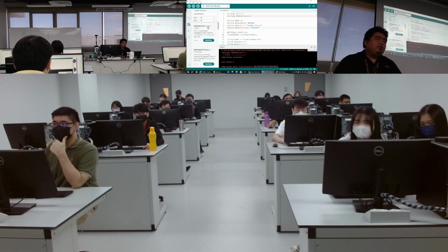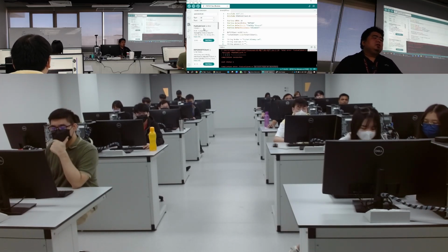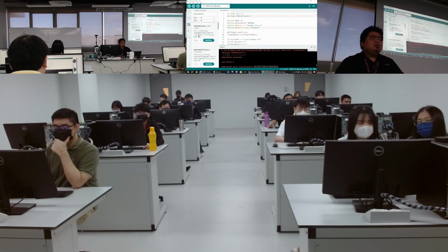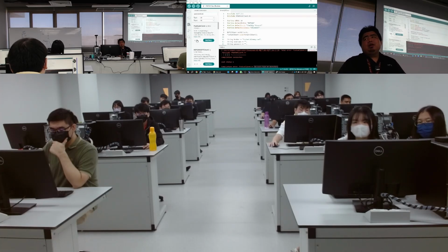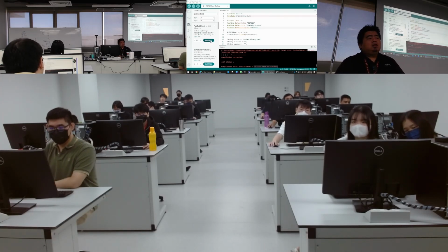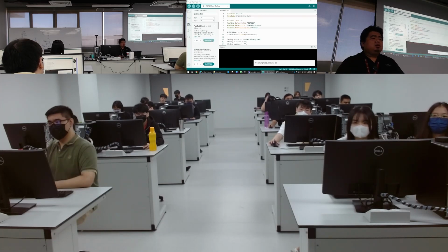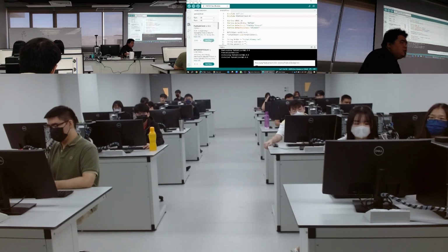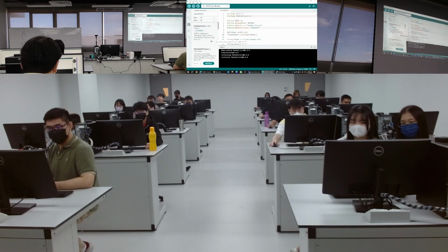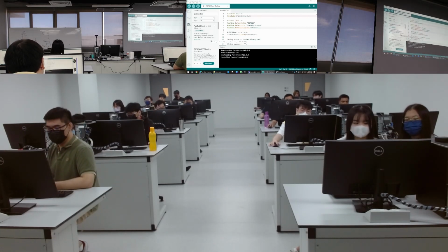Okay, so you have the PubSubClient library by Nick O'Leary, version 2.8.0. Then you click install. So it will install the library for you. Okay, Denny? Can install?